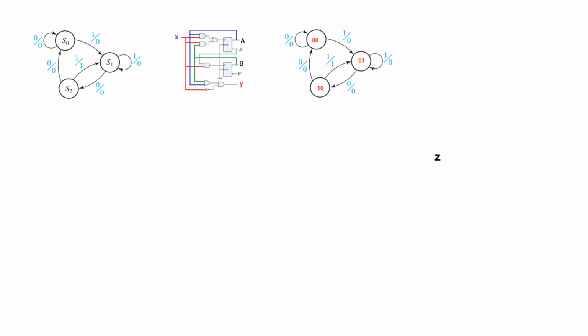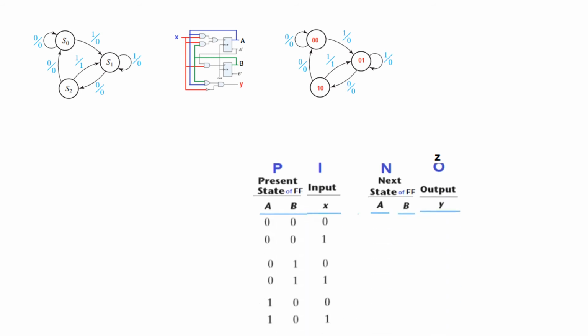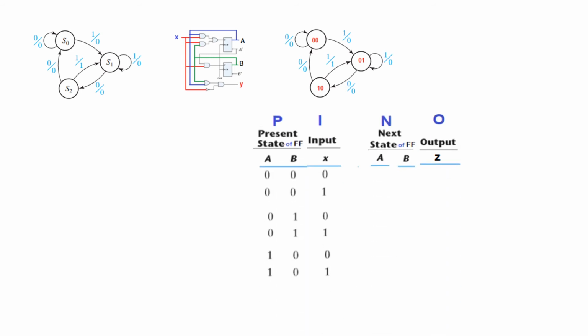And now that we have incorporated flip-flops, we just need to now draw what is known as the transition diagram. Sometimes it is also called transition table or state table. It's exactly the same, no difference. In the state table we just write S0, S1, but in the transition table we write AB for the two flip-flops. Okay, now the options we'll have, we had done this in video number 1 also. So those of you who have difficulty can go to video number 1 and revise.